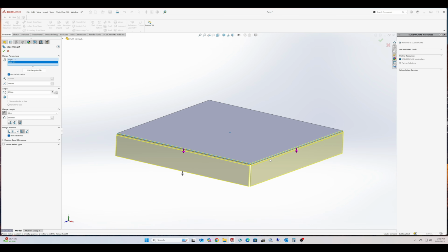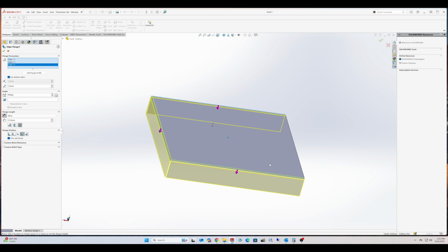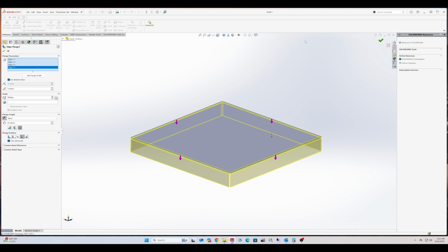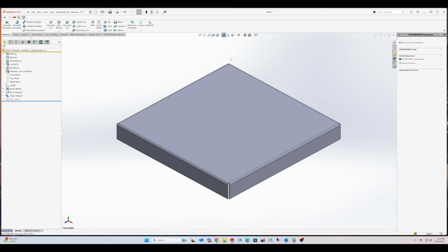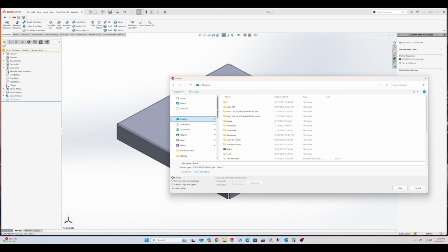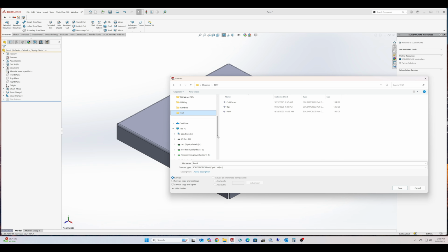But there are cases where you have a machine, forming tool, or a corner former, and you need it to do a special type of edge. And you don't necessarily want to show it. You can go back and show it in the 3D view if you want to. There's ways to do that, but that's not what we're talking about right now. We're talking about how we manipulate this flat pattern so that we can get those treated edges in there, so that when we're doing that NC file and taking it out to the machine, we get the corner that we want. Now, one thing about SolidWorks is always let SolidWorks work for you.